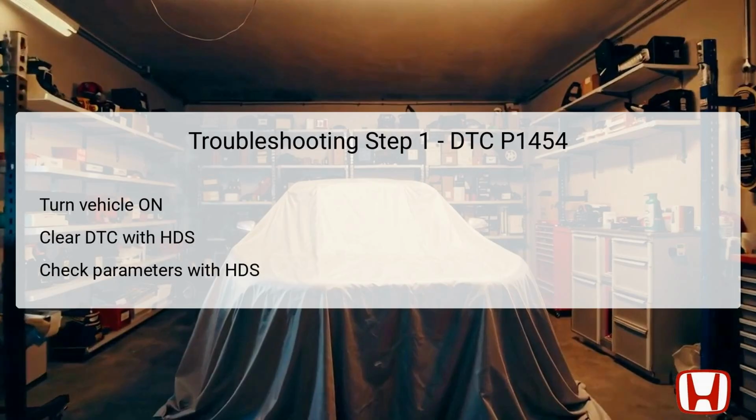The first troubleshooting step for DTC P1454 involves preparing the vehicle for diagnostics. Begin by turning the vehicle to the on position, ensuring all electrical systems are active without starting the engine. Next, utilize the Honda Diagnostic System, HDS, to clear any existing diagnostic trouble codes, DTCs. This action resets the monitoring systems, allowing for a fresh evaluation of the vehicle's operational status.